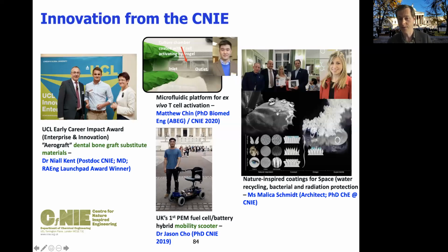I see that once there was one question, there are many more. There was one on solid byproducts removed from microscopic pores in catalysts. Indeed, that's called catalyst deactivation. In a porous catalyst, you may have solid particles deposited in there, for example coke, right? And what we can do is mitigate this effect by having better transport. If you have better connectivity, it's just like traffic jams: if you have better connectivity of roads, you could go around, right?